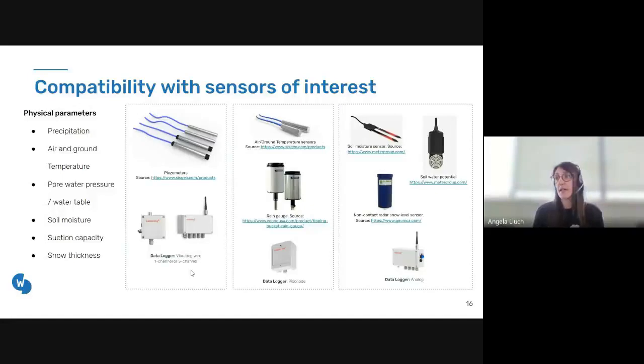Precipitation and changes to the hydrogeological conditions are some of the parameters that can trigger instability on a slope. In general, the presence of water increases the weight of the ground. It also increases the ground saturation level. It can also cause the internal and external erosion of the ground, and in general, decreases the shear strength of the ground. It's for that reason that parameters like, for example, the pore water pressure or the phreatic level are commonly monitored in these scenarios.